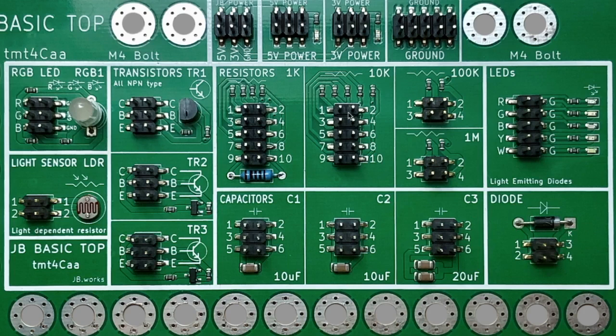So just looking at the different components we saw earlier on, this is the transistor. So you notice it's got the circle with the wee arrow in it. Resistors. Now these have a squiggly line to represent them, but you can also use the square symbol, or rather the rectangle symbol, so either one is fine. And likewise capacitors with the 2 plates, and then you have the diode and the LED diode. Remember, it's got the 2 arrows pointing outwards. And then the light dependent resistor is a resistor with 2 arrows pointing inwards.